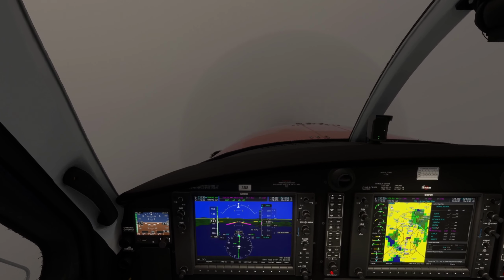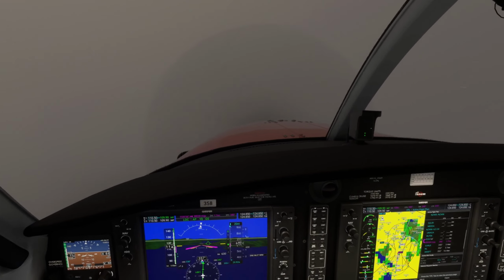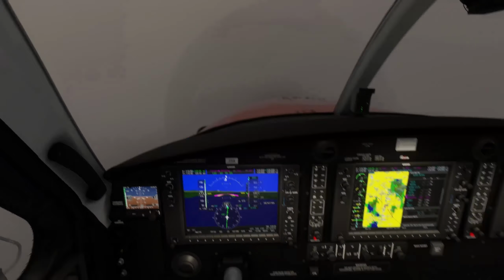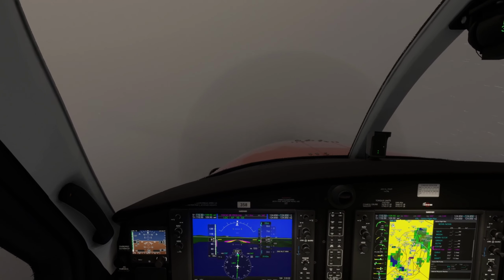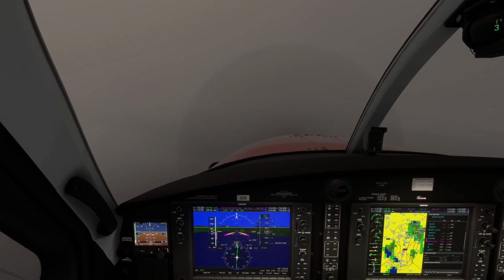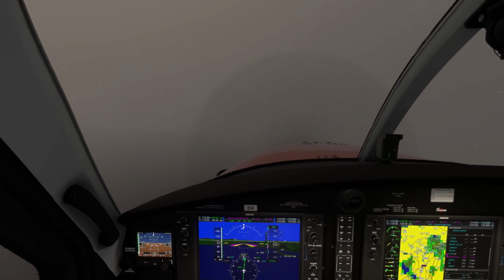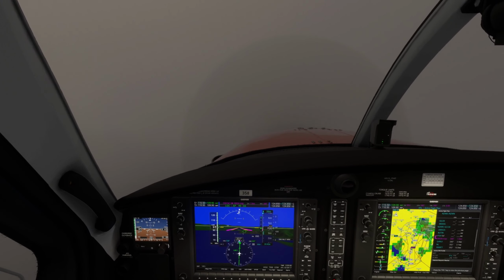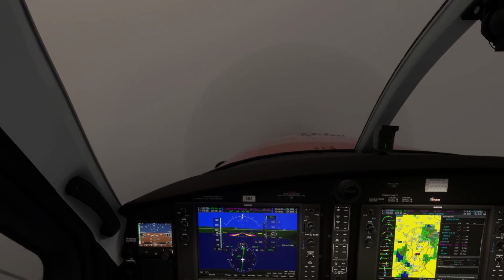Through second stage of flaps. About 1.7 nautical. And we will put full flaps down. Just watching my airspeed, just don't want to drop too much. 500. Alright. So we've got a crosswind coming in about 9 o'clock, about 8 knots, 7 knots. So not too bad.